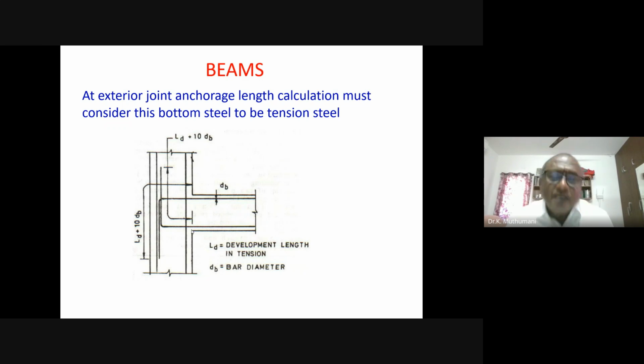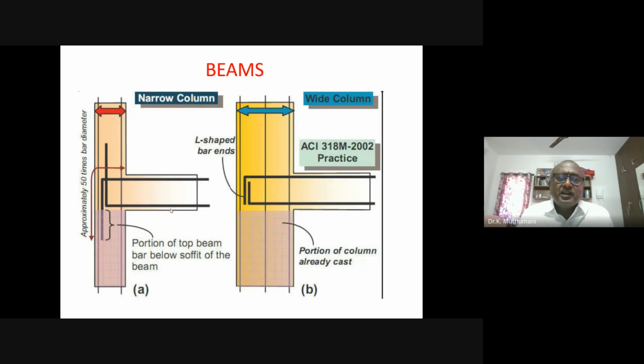Please understand that, because of the ductility of a beam, the way in which a hinge is to be formed here, the way the hinge is to be formed here, you are arresting that and trying to create a weakness in the joint, and the joint fails. And so if your detailing is very bad in the joint anchorage, it is serious, I'm telling you. This is the example I am telling. Suppose you put the concrete up to here and say I am not able to insert like that, and then try to bend like that. That is not possible. So either you have to increase the section.